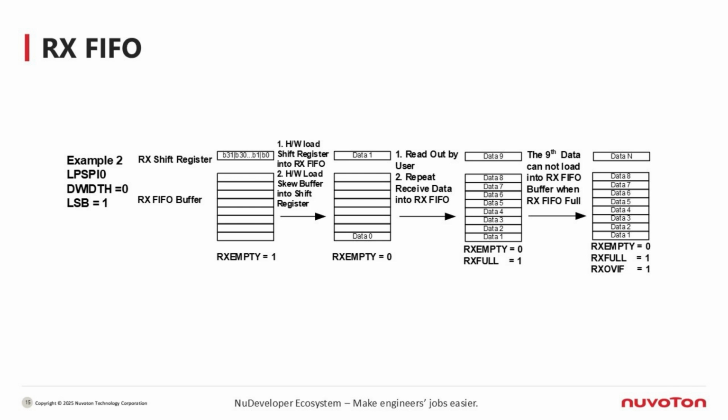For example, if you send 4 pieces of data from the TX FIFO in a row, once the busy flag goes to 0, indicating all 4 pieces are sent, at the same time, the RX FIFO has accumulated 4 pieces of received data waiting to be read. So in your application, you need to pay attention to both TX FIFO and RX FIFO capacity and status to avoid RX overflow when TX is sending data.